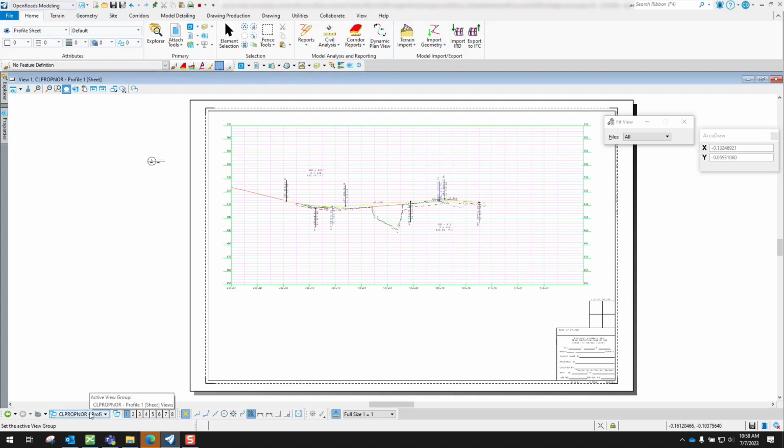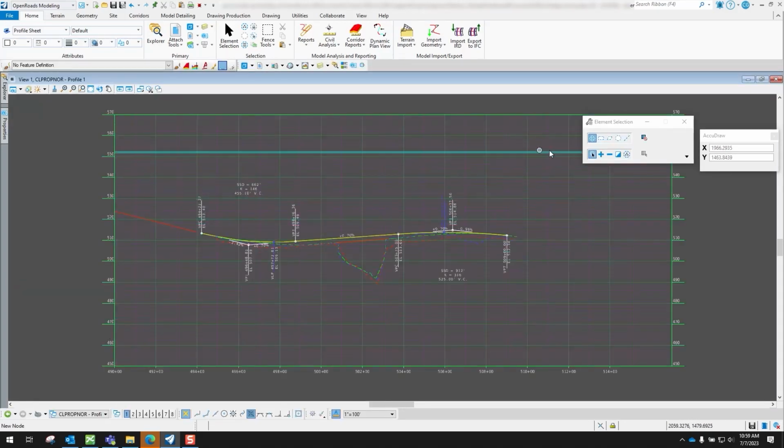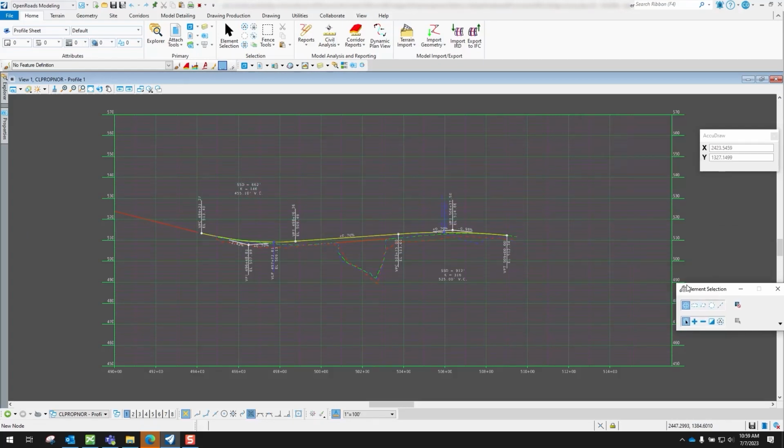And if you need to make some modifications to it, you'd come into the actual drawing model of it, which is this right here. And this is where you can come in and put in that legend for your 30-foot left, 30-foot right, and also the center line. For your profiles, you can put in your text inside of here. Basically, get this set up exactly the way you want for your particular bridge survey that you're doing. Another thing that you can do is if you would need to rename this, you can do that also.